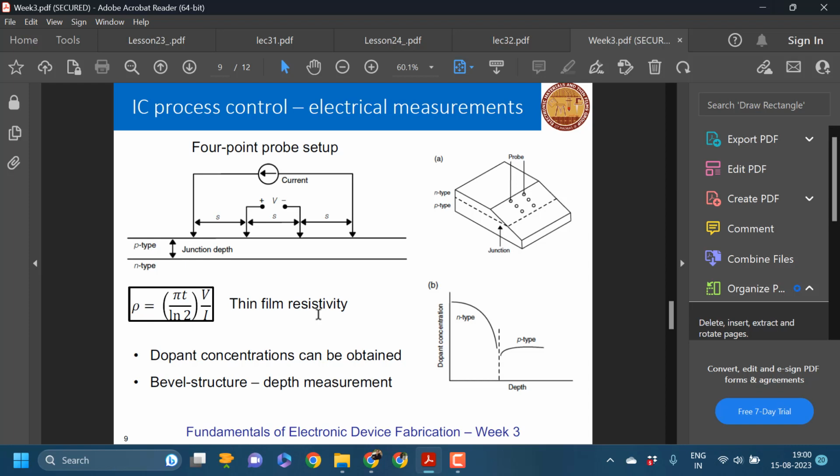Electrical testing is to make sure that the component is correctly conducting and functioning as required. Next is physical parameter measurements, whether its dimensions are within the required limit or not. And finally, defect measurements, whether when we were doing heat treatment or polishing, etc., some physical defects or some stress or strain was induced into this particular wafer.